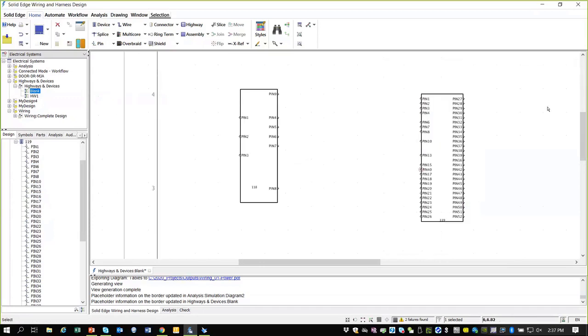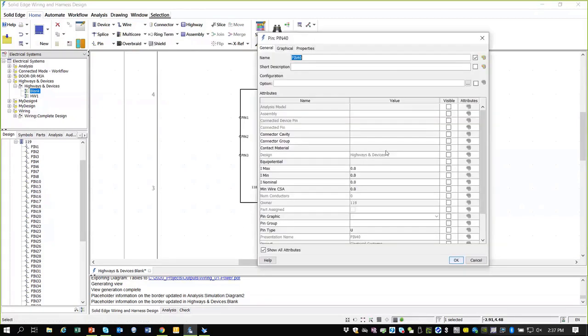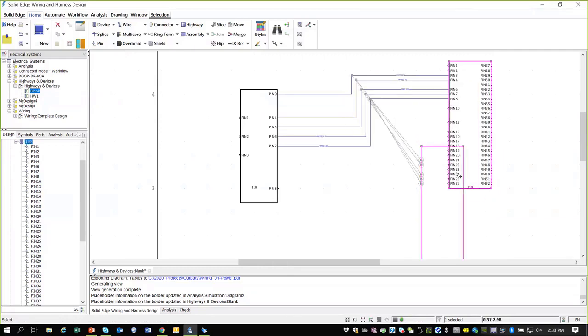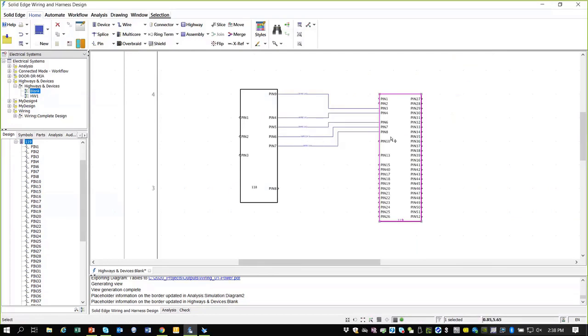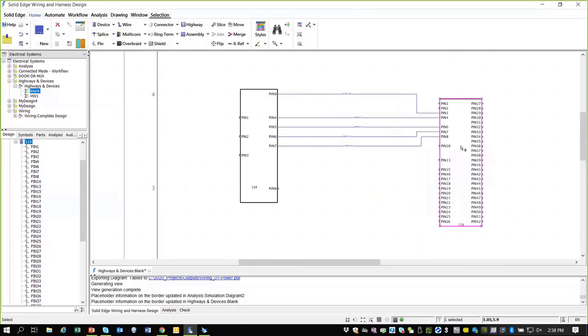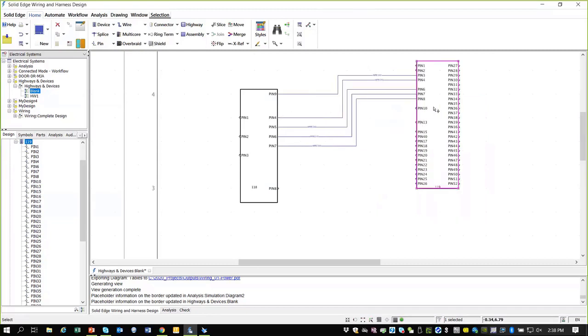Okay, so really helpful. To wire up multiple wires, a nice advanced feature here: multiple wires. I pick these 5 pins, and I want to wire them over here, and it automatically does that for me. And again, the intelligence of the application: if I move this around, it's aware that it's wires, it makes sure that they don't conflict with each other, and does the routing for me to keep that straightened up.